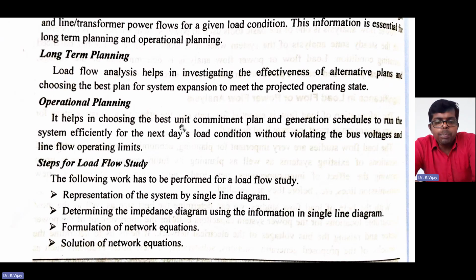Next, what are the steps for load flow study? First, we need to represent the power system by using a single line diagram. When solving problems, mostly they will mention all this with the single line diagram. If not a single line diagram, they will give the values for the buses. Say for example, bus 1 to 2, what is the impedance? Bus 2 to 3, what is the impedance? 3 to 4, like that. They will mention the impedance. You need to frame the single line diagram from the data. So that is the first step.